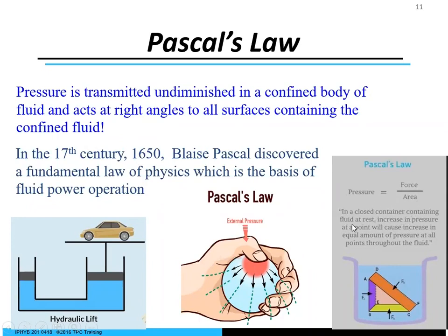In a closed container containing a fluid at rest, increased pressure at a point will cause an increase of equal amount of pressure at all points throughout the fluid. Also, as we get to know some of these other formulas, when you put fluid in a cylinder and you put pressure on it, what's also going to be created is heat. So we need to look at the heat. When you're dealing with hydraulics and the packing, when we're trying to repack the cylinders, you need to really know what type of packing, what type of seals I'm going to have, or what the temperature readings are of each seal, and the types of seals in there.